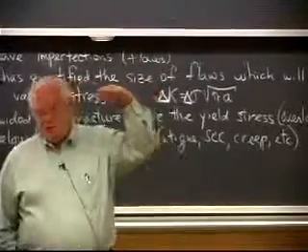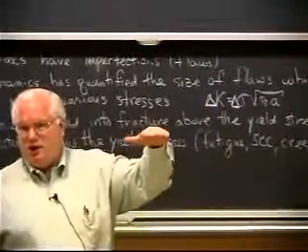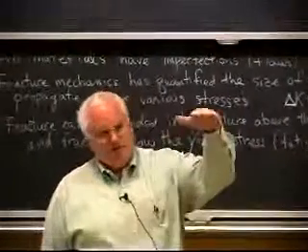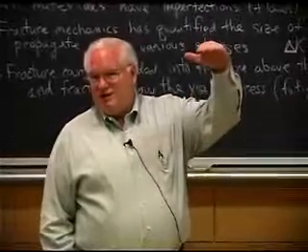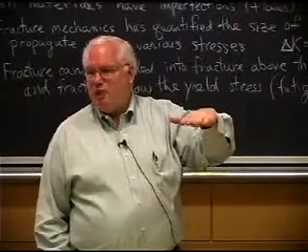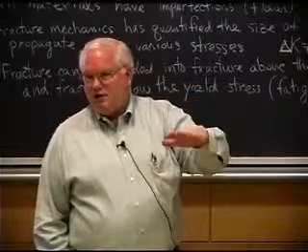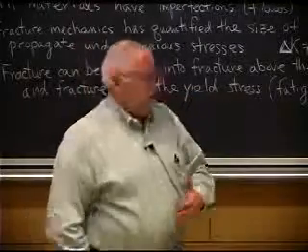Typical fatigue stress for the 7075-T6 aluminum should have been like 35 KSI for a practical fatigue limit. It doesn't have a true fatigue limit, but you ought to be able to operate it there. Since it's got 73 KSI strength, you ought to be able to operate it at 50% of that, like 35 KSI. But in fact, it failed at 8 KSI. Why? Because you had corrosion going on too. So stress corrosion cracking can be very insidious.